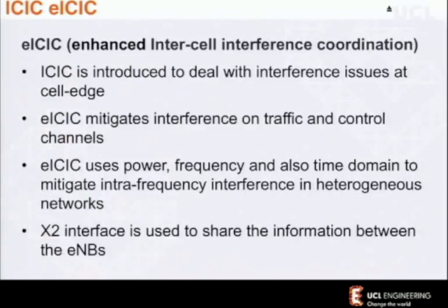You can also flip that on its head a little bit. The other problem of being in between two cells is you're getting information from either side. Some of it you want and some of it you don't. So you're getting interference from other cells. However well you do your frequency reuse, there's always a certain amount of interference. Can we coordinate how we do our resource allocation in the two cells when you're in the middle, so that you're not getting interference? This isn't quite so heavy a use of the X2 interface, but still it is a joint processing between our cells.